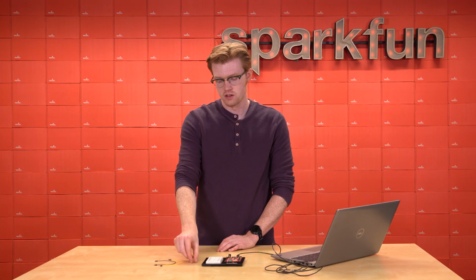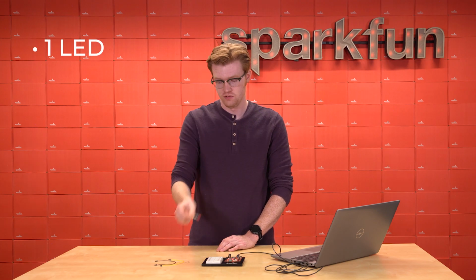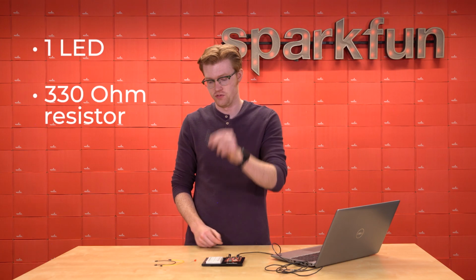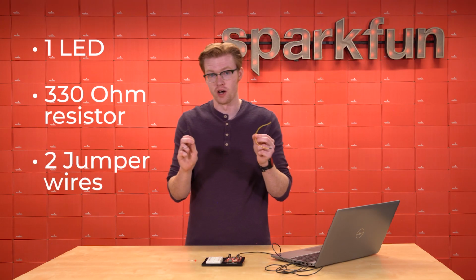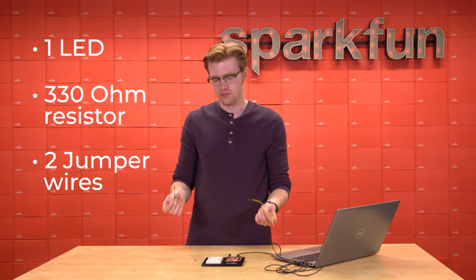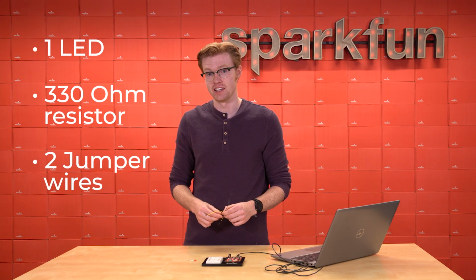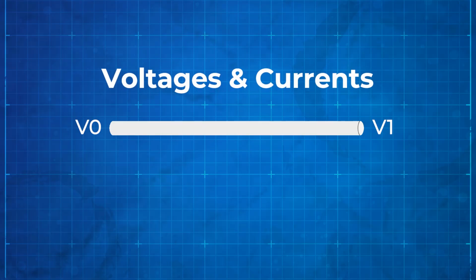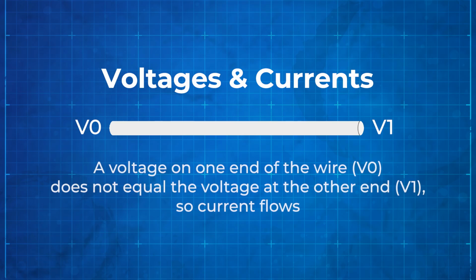For this circuit, you'll need an LED, a 330 ohm resistor, and two jumper wires. And our job is to figure out how to put them together to blink the LED. At the core of every circuit are voltages and currents. When there is a voltage difference between two connected points in a circuit, a current will flow between them.